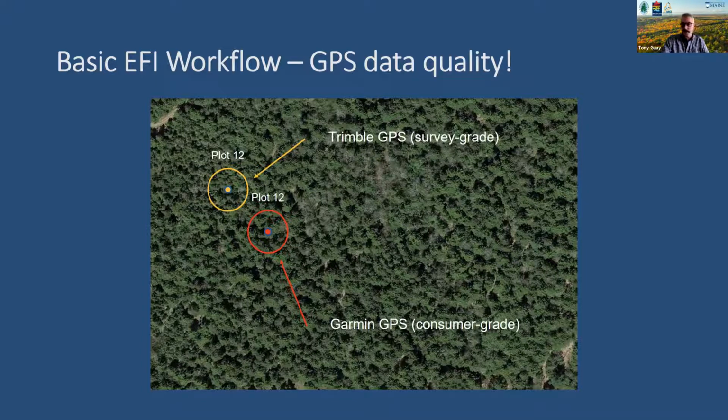On the flip side, using survey grade accuracy with your plot data locations, you can achieve very good results. There are other factors that go into this. How dense is your point cloud data? The standard QL2 state LiDAR is not the densest, and it's also leaf off. So those are a couple of challenges with using the statewide data, the free stuff for this type of work. But we have done it and achieved some rather good results when you're able to have plot data that has been collected with survey grade GPS. That, I would say, is really key. The other thing is we've tried this with variable radius plots, with prism plots, and then of course with fixed radius plots, and pretty uniformly have achieved better results with fixed radius plot data that has been located with survey grade GPS. So those are really, really important.